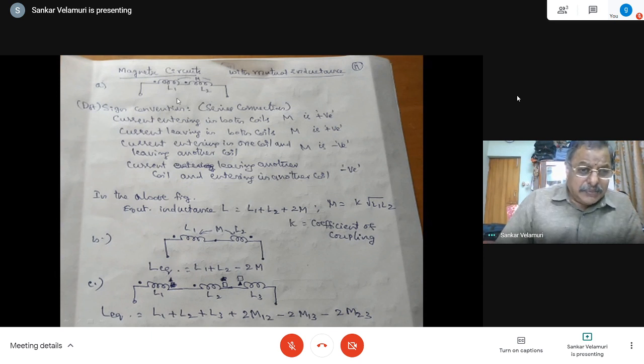It is implied. Because the direction of the current in L2 and L1 will be the same in that context, although the current is leaving both the coils, still the mutual inductance between them will be aiding with respect to each other. Okay, it aids, A-I-D-S.